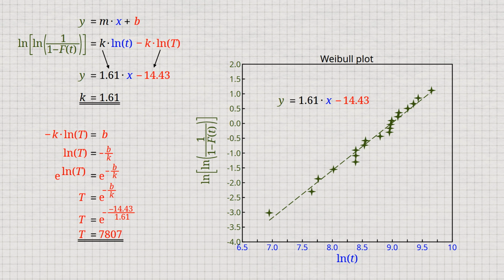Generalization to the population is not possible without further ado. If we were to examine a second statistical sample, the Weibull line we would obtain would be more or less different from the first. For this reason, the graph is often extended to include a confidence interval. The confidence interval indicates the limits within which the Weibull line can be expected to lie and the probability with which it reflects the failure probabilities of the population.